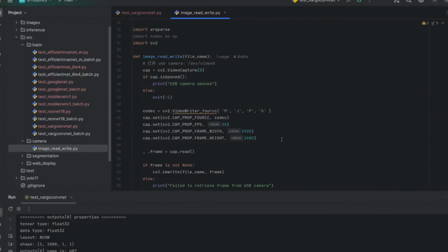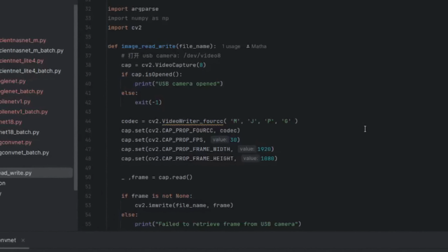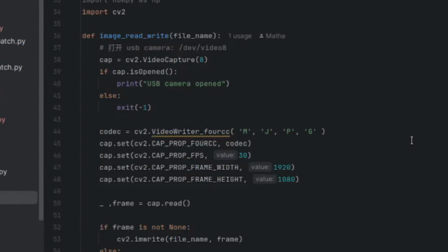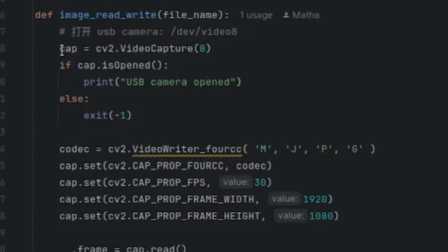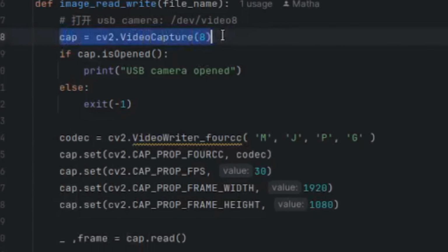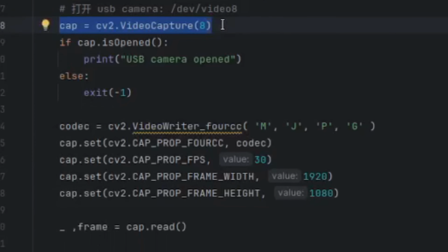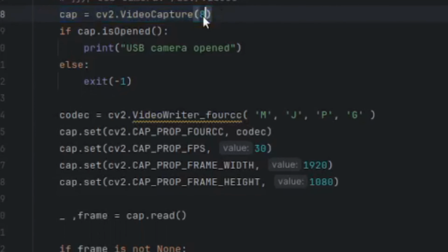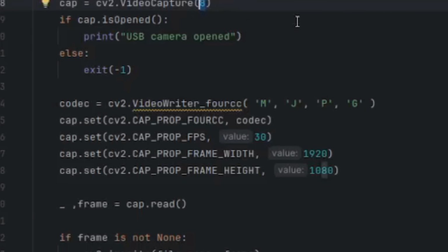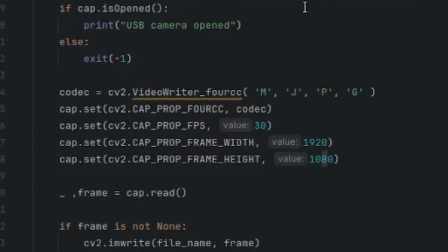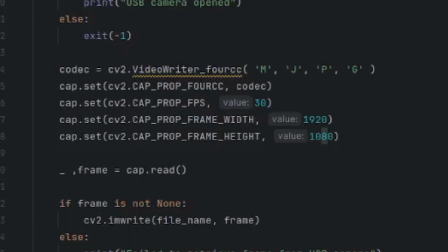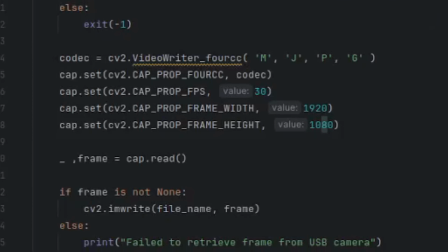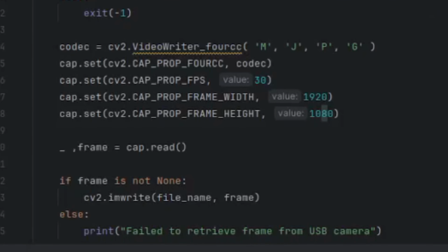The RDK board supports OpenCV, of course, since it's running under Ubuntu. The key thing in OpenCV is when you're doing a video capture, the video index is for some reason number 8. I mean, there's a good reason for it, of course, but I haven't dug into it. So watch out for that. You have to use an index of 8, not 0 or 1 that we're traditionally accustomed to.